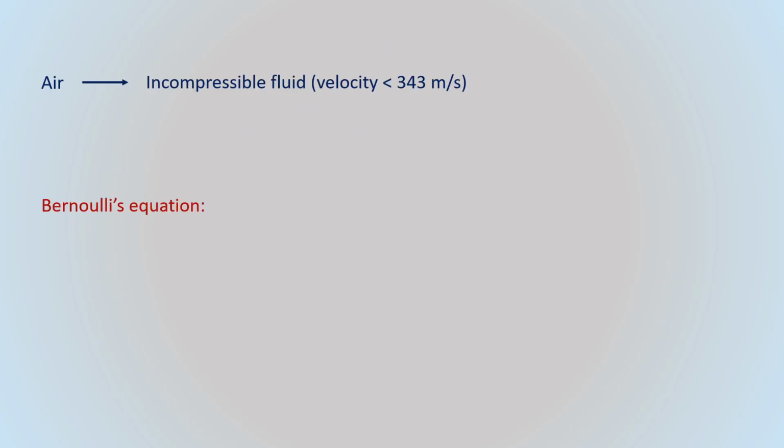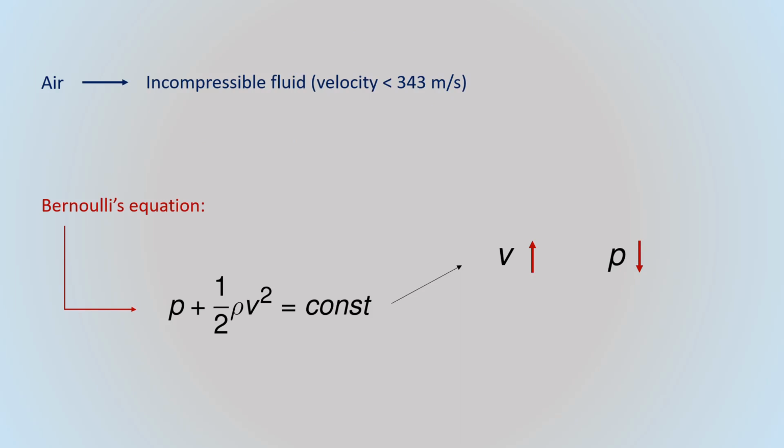So, let's explain this phenomenon using simplified equations. First of all, we are considering air as an incompressible fluid, because in doing so, the Bernoulli equation is valid. The Bernoulli equation states that increasing the speed of the fluid, the static pressure decreases and vice versa.